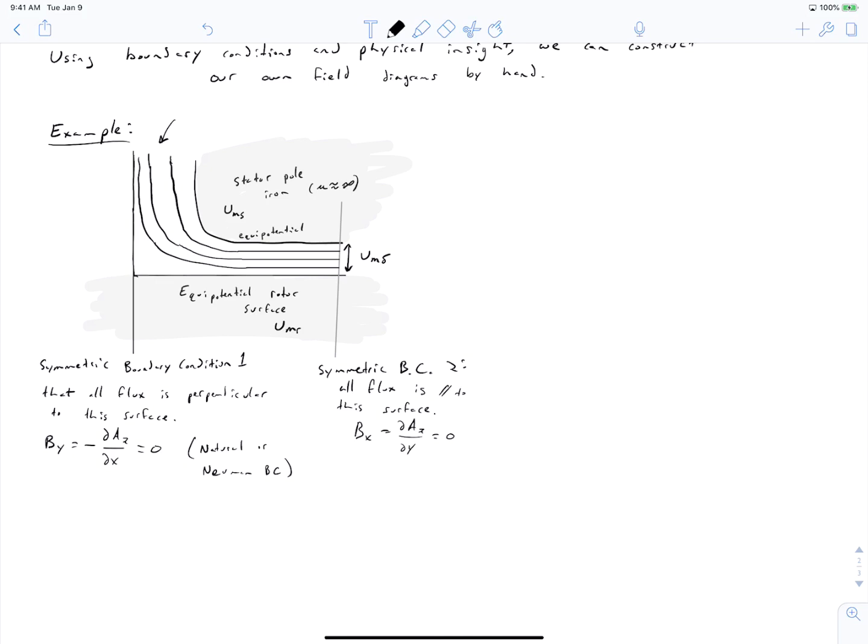And now we'll draw our flux lines. And in this case, we're going to draw them in gray. And so starting on the right side, we see that our flux lines should all be parallel. And that is, we know that they exit and enter the high permeability surfaces perpendicular to the surface, and there's nothing to cause them to contour in the air gap. So we're drawing these all as perpendicular lines until we start to get some curvature. And when we have curvature of our surface, again, they have to exit the surface perpendicular, but they will arc down to enter the next surface perpendicular.